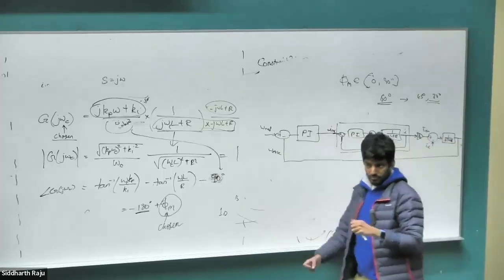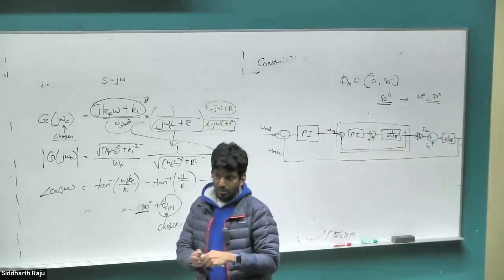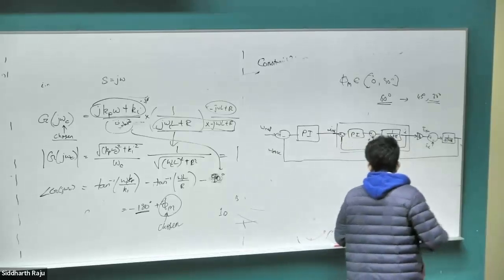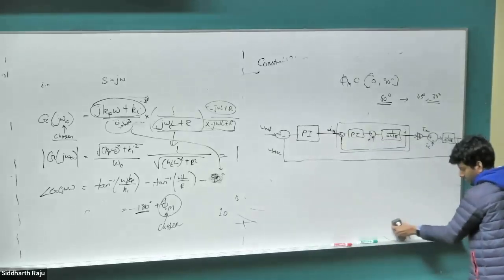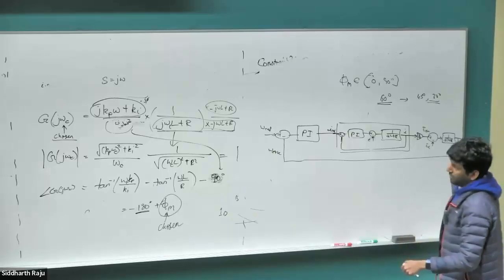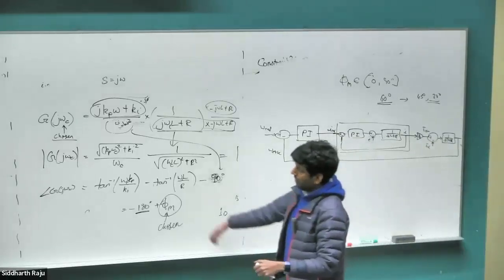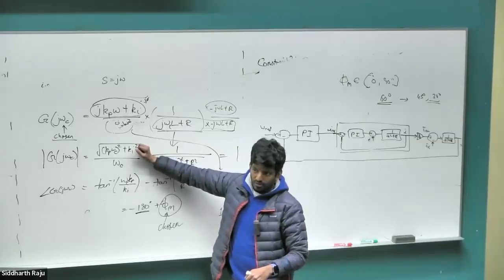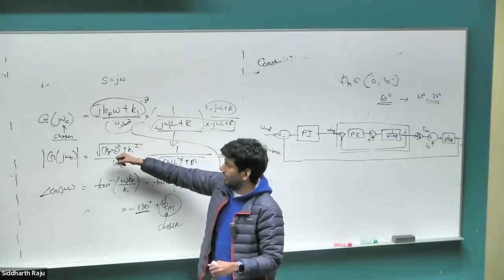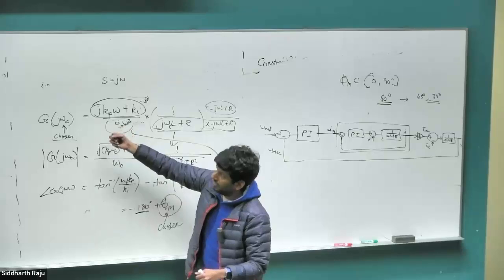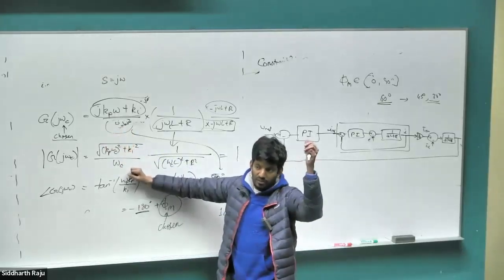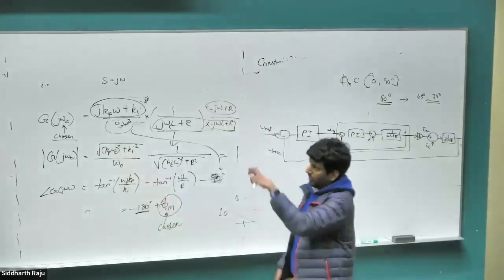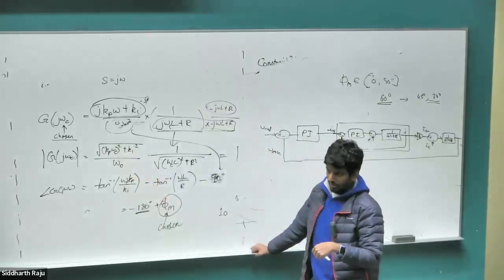Yep, Ben. Where does the 90-degree bound on phase margin come from? That will come from the fact that our PI controller has only a single zero. Right? If you had, let's say, SKP plus KI the whole square, then you can push it to negative 180 degrees further out. It's just from the single zero that we are putting on the numerator. Okay.